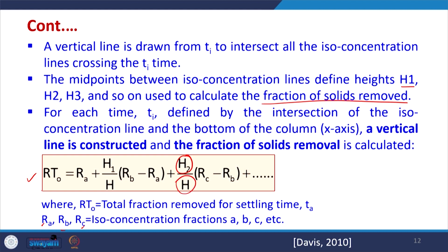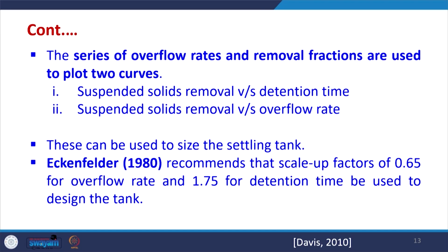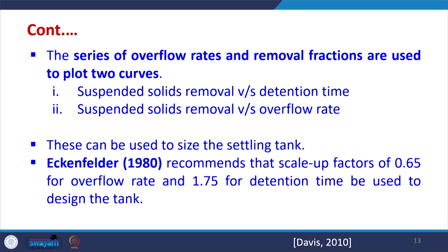From this we can calculate the total percentage which is possible to be removed in this time fraction, and the overflow rate is also known. Through this we can plot two types of graphs: one is suspended solids removed versus detention time, and similarly suspended solids removed versus overflow rate.